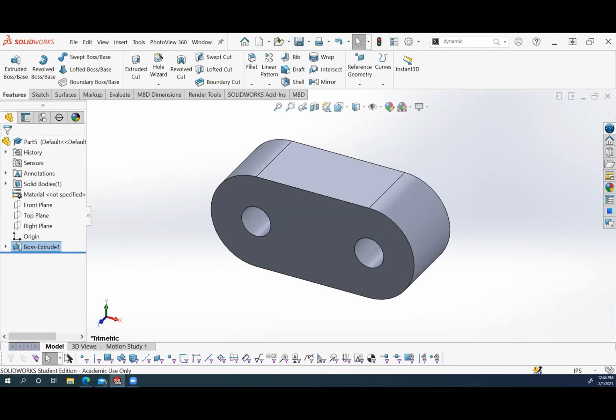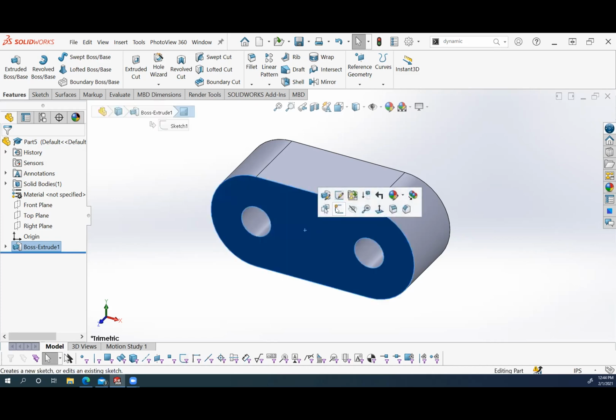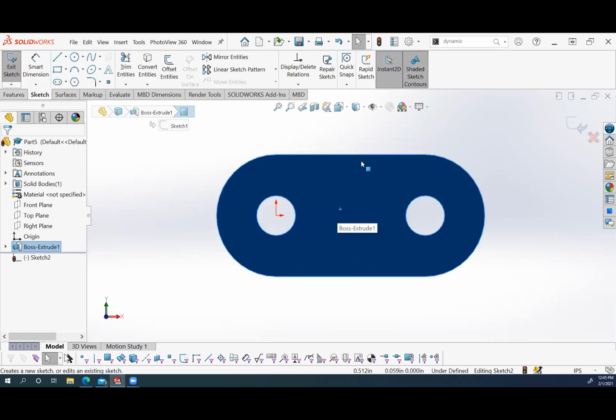Now we are going to create the boreholes. So we're going to select this planar face of the solid. So click there and click Sketch. If your solid isn't going to normal, which is just where it goes to the face that you're drawing on, you can hit Control-8 on your keyboard to do that.